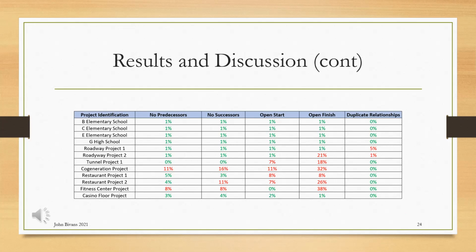An activity is considered to have an open start if it does not have a predecessor with a finish to start relationship. This may result in a skewed representation of the impact of the activity on the critical path. Of the 4 projects that failed to meet this metric, the average delay was 29.25 calendar days. This delay average is very close to the average overall delay of 26 calendar days, indicating that the impact of this metric within the bounds of this study is inconclusive.